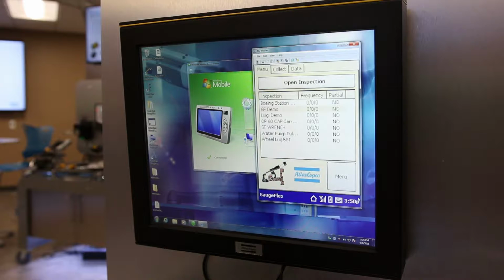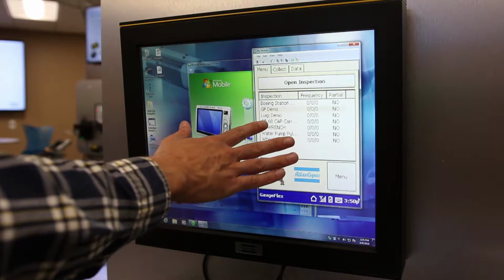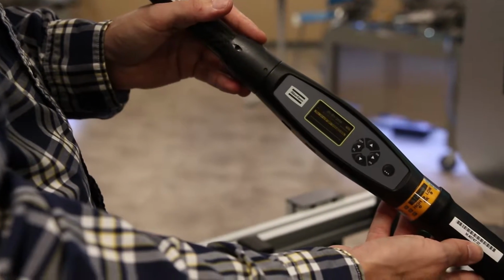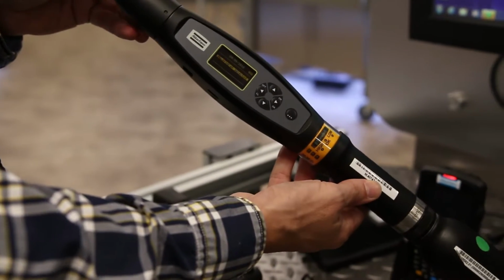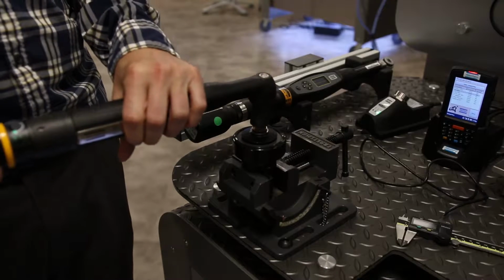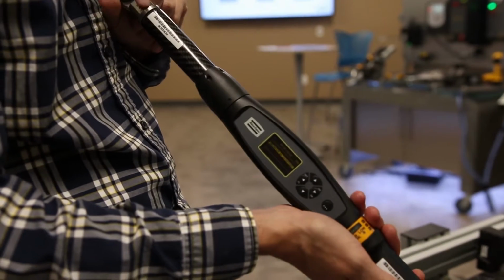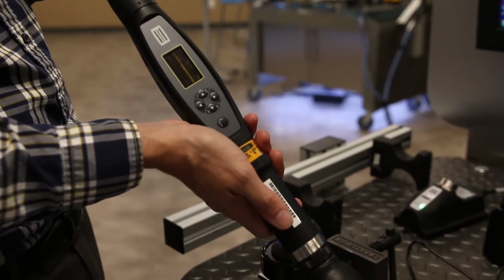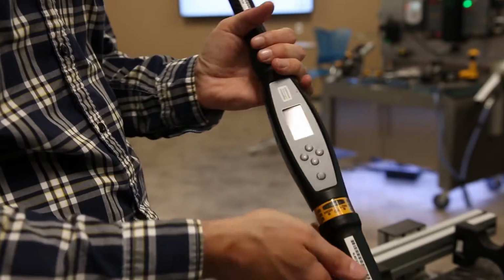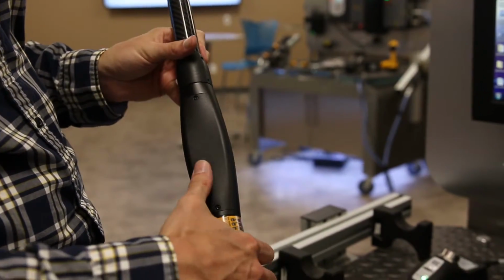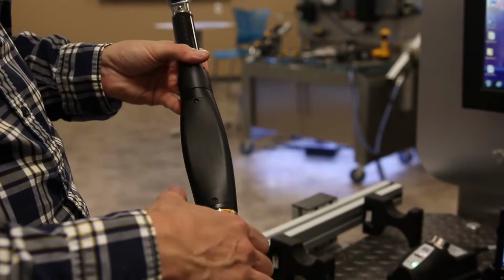The first demonstration is our Opt60 cap carrier inspection, utilizing power focus and a DC tool. In this application, a soft joint is tightened with a tensor ST tool. Fasten the joint using the DC tool. Show your customers that the torque reading is displayed on the PF4000. Use the ST wrench to check the torque on the joint. The ST wrench tool is used in conjunction with the GaugeFlex to perform the residual tests on this actual fastener and is connected to the GaugeFlex via a Bluetooth connection.